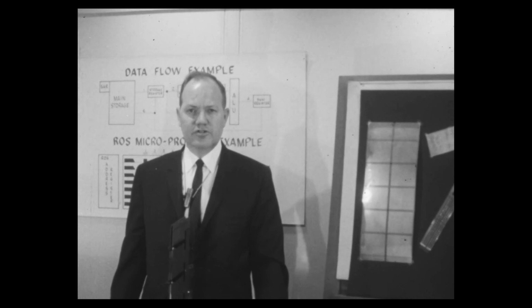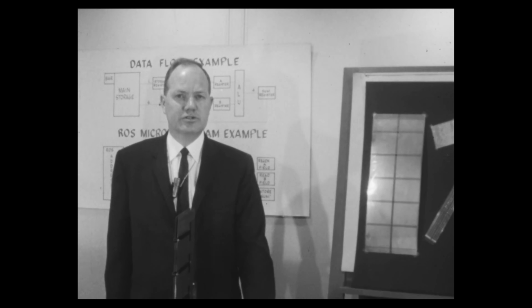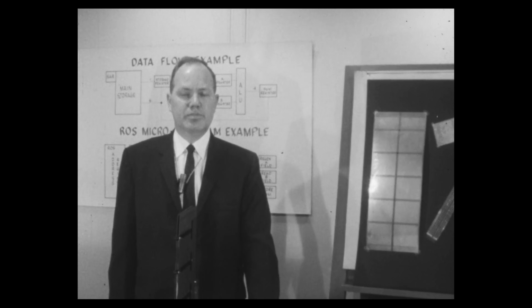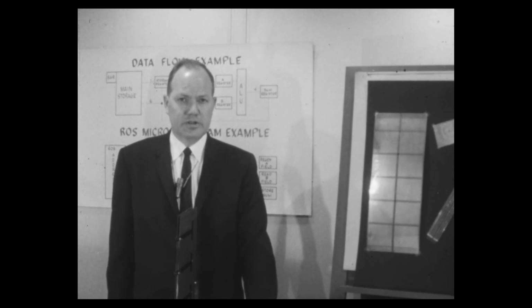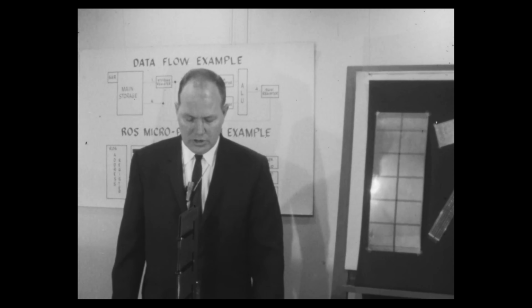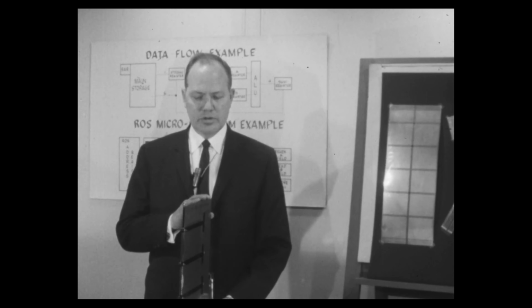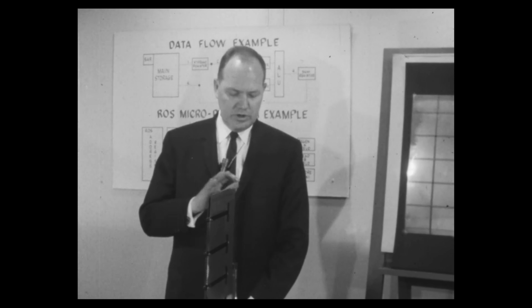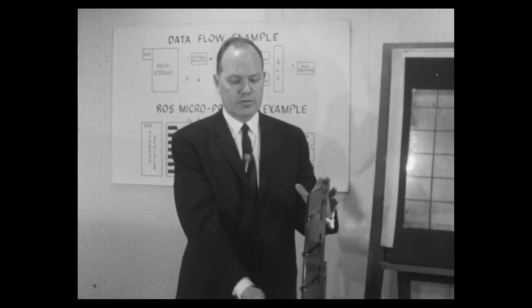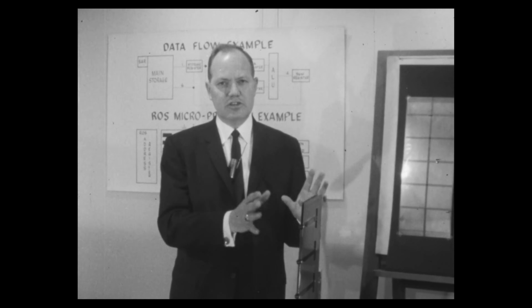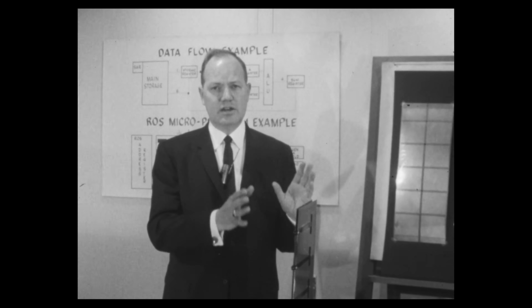Now, let's get to the second major advantage of read-only storage, and that is the compatibility feature and capability that it allows us. To run a machine in compatibility mode, we would in effect set aside the normal read-only storage with a 360 instruction set. That's fixed. The engineer determines that, and it stays that way from time here on out until such time that he generates a change. The application programmer never can affect that.